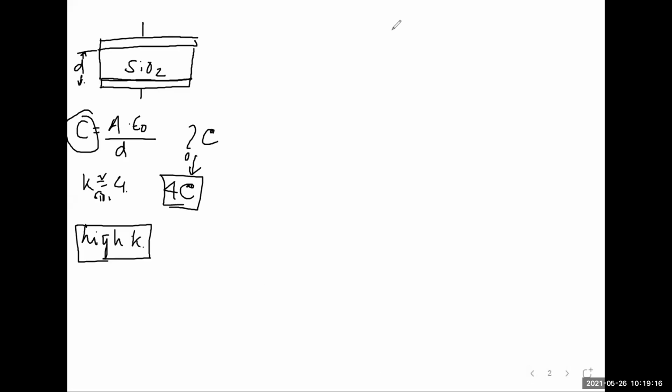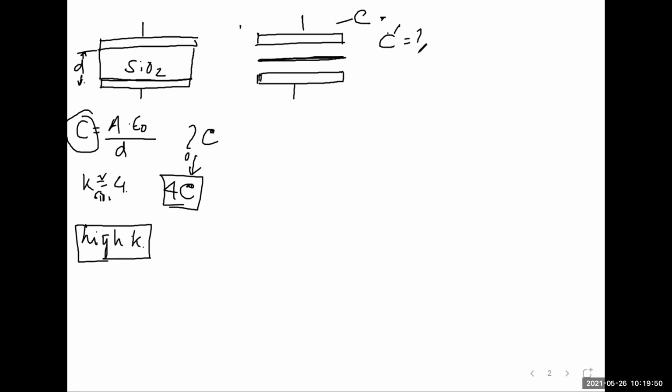All right, now let's do some more. Capacitances are your bread and butter in IC design. Okay, so I take again the same distance and everything, and let it be air. Now I put a small sheet of metal. I cover this whole area with a thin sheet of metal. So previously this capacitance was C. What will be the new one? What is the new C dash going to be with the metal sheet in between?